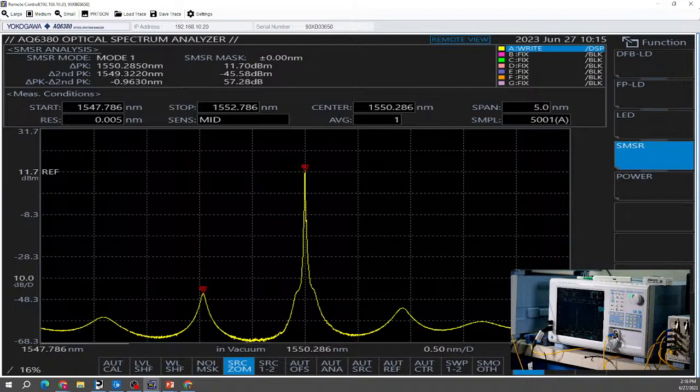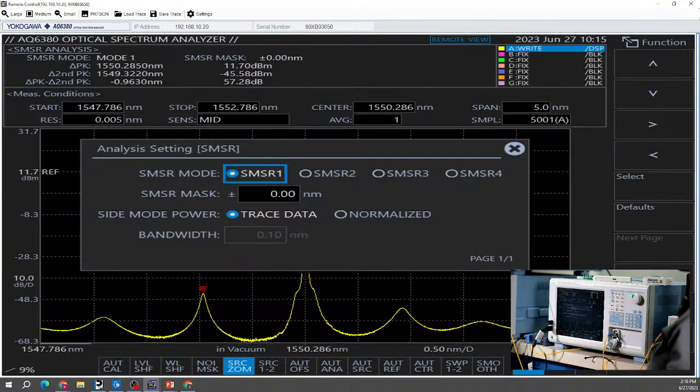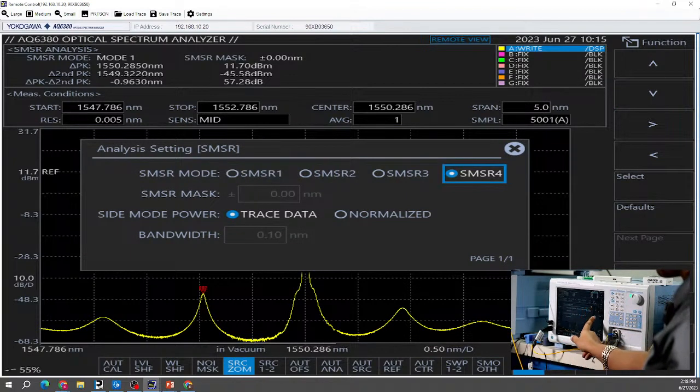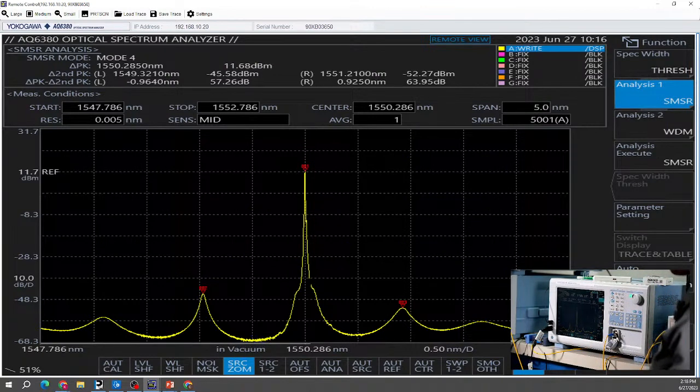Yeah, I mean, it shows a pretty good description of the peaks, and of course, we also have, with that SMSR, you can do parameter settings to sort of automate as well. So we do that, and then it executes. And so now we're showing 2 peaks instead, just like an auto SMSR analysis. Pretty effective, shows those 2 next peaks pretty well.